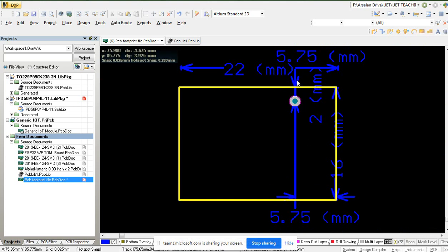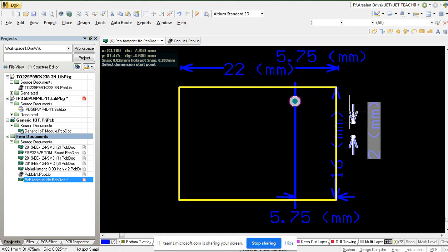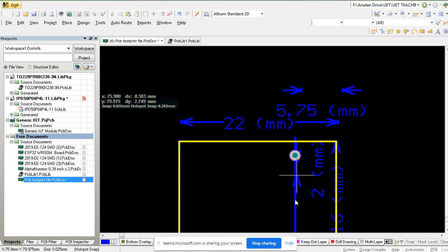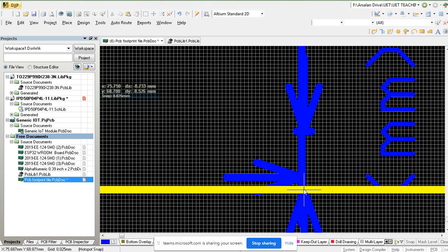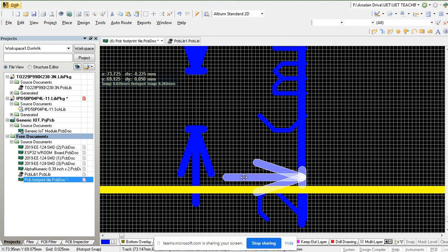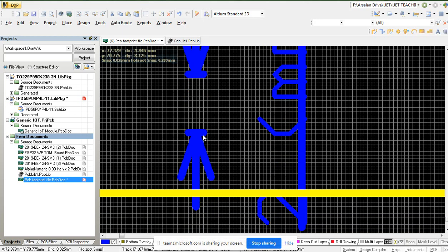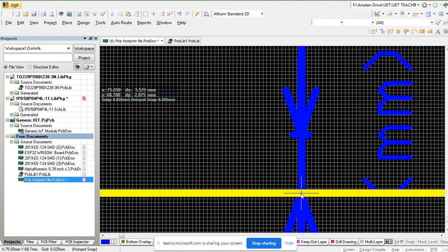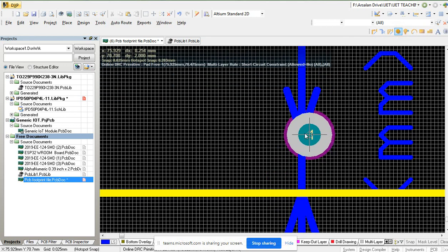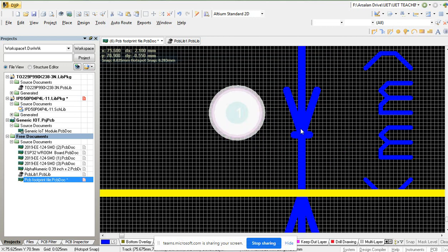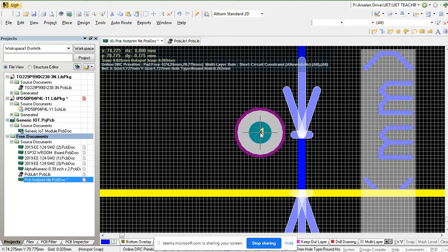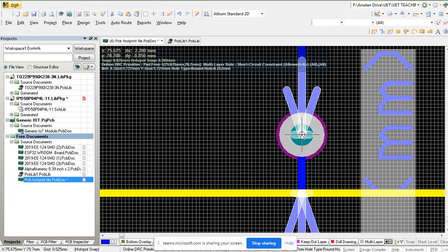No issues over here. Similarly, this time I will again take this track and I will just maybe rub this one, and now this time on the lower side, let me just rub again this track over here. This one is not required at present, so I will just cut this again and place it. Now you can see zooming in is very important, so you can place it very carefully, because if the lines are not placed accurately, you are going to have a problem. So I will just select this, and you can see when I have selected it, if I move it, this is exactly at the center.